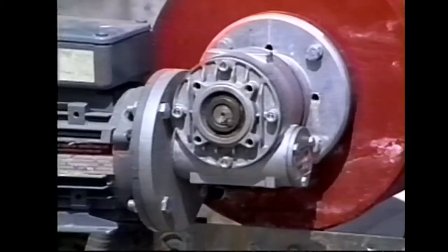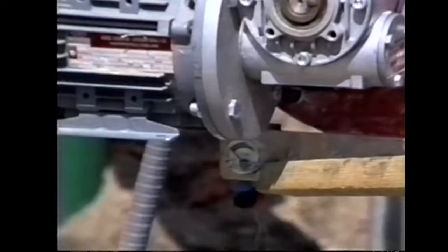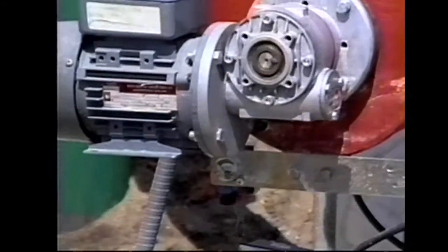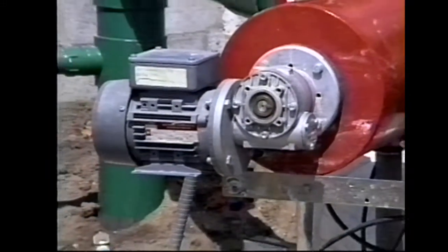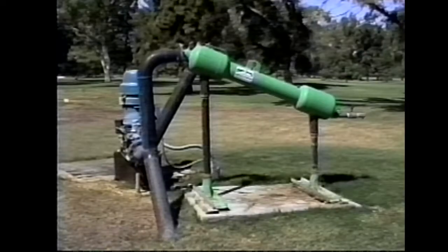For low-pressure installations, the backflush mechanism must be rotated using an electric motor, as seen here. An electrical pressure differential switch is used rather than a hydraulic switch. With automation, these units can be effective in very dirty water conditions. The next devices are used primarily for well water. However, they are also found in some surface water situations.